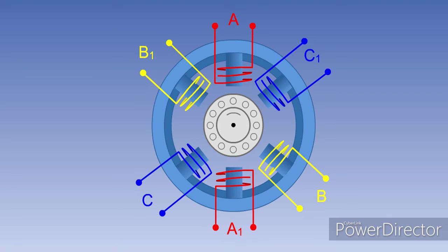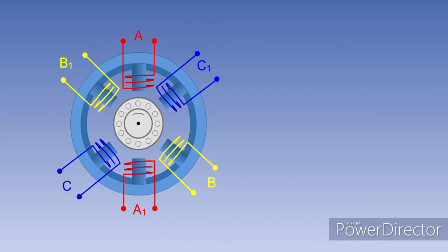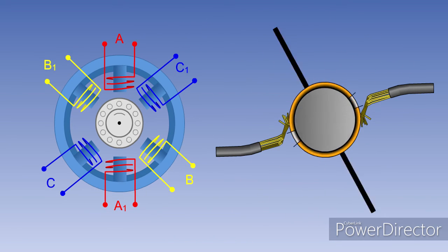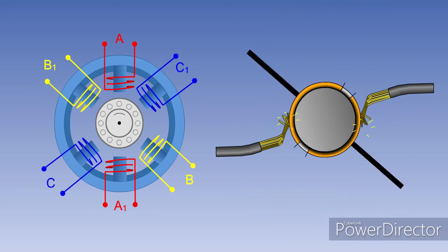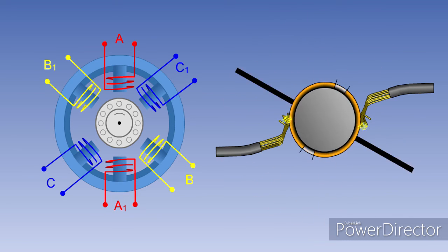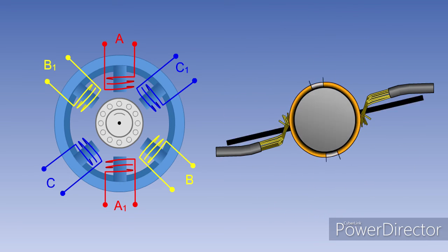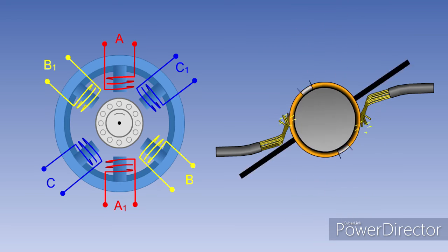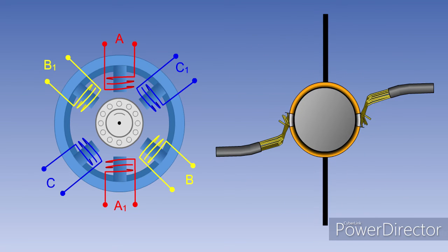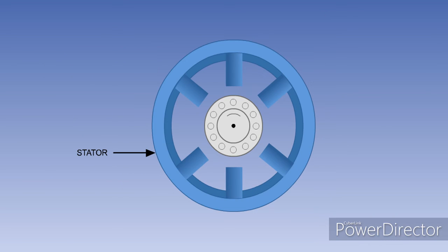In this lesson, we will look at the construction and operation of electric motors using AC as their power supply. The great advantage that an AC motor has over its DC counterpart is that it doesn't require the use of a commutator, so the problems of arcing at the brushes is greatly reduced or even eliminated. Whether the AC motor is single or multi-phase, the principle of operation is the same.